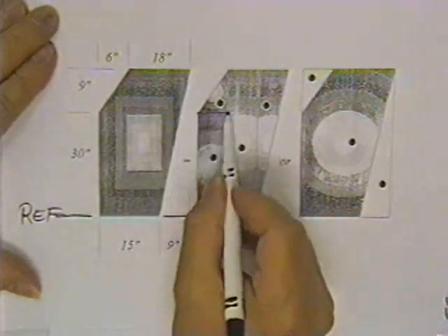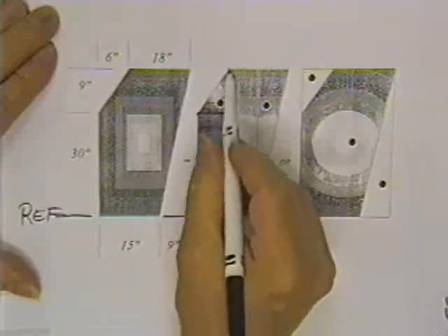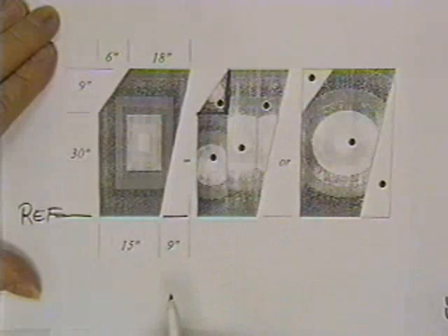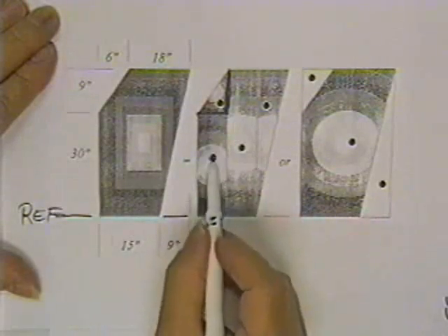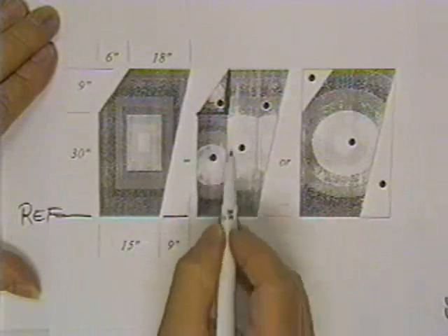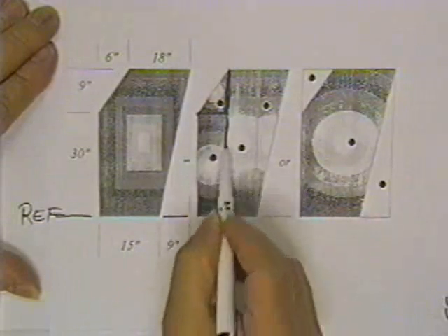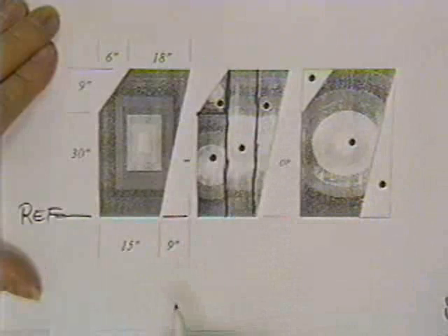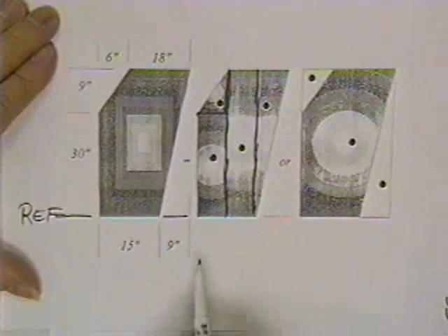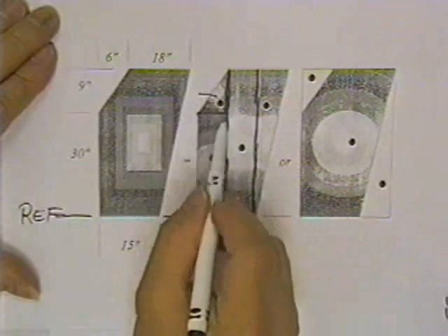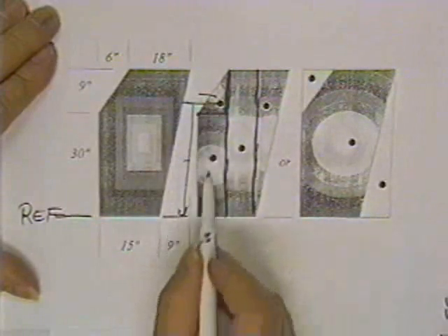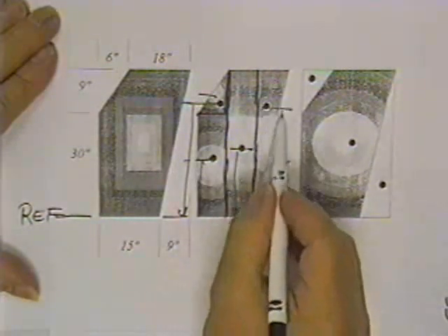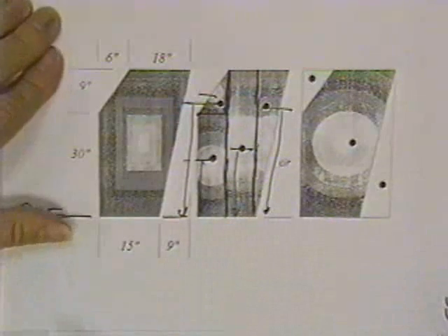Here's one way you could split it up. You could split this up into a triangle, because I fully know the area of the triangle, and I know its centroid is 1/3 of the way up. That would leave me a rectangle here, and I know its area and I know its centroid. I could leave this rectangle up here alone, and then finally I'd have another triangle with those centroids. I could say area 1 times y1 plus area 2 times y2 plus area 3 times y3 plus area 4 times y4, and I have the answer.